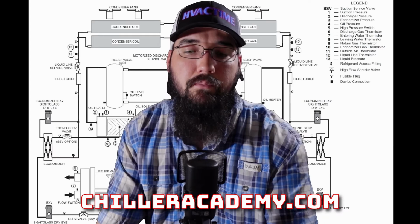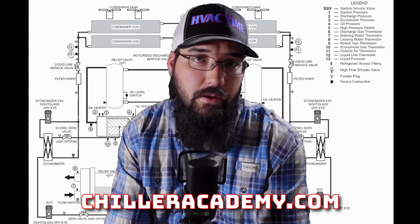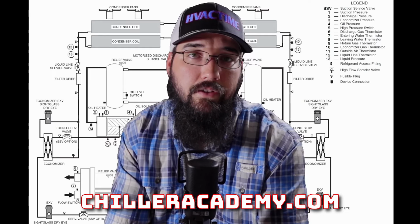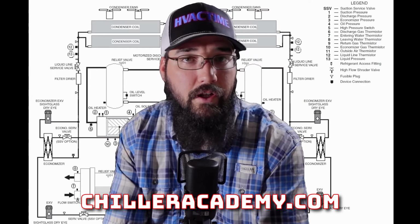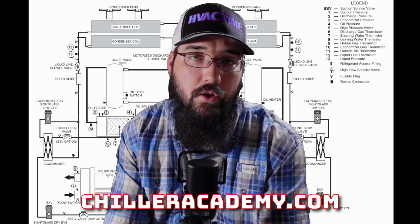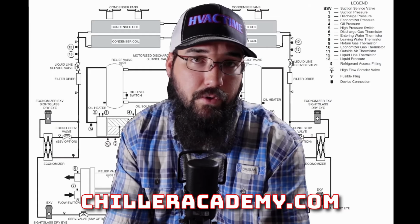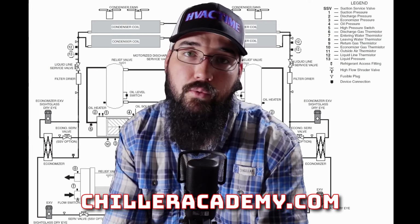So they'll put both together in the same compressor. Essentially, what that typically looks like, they'll use the slide valve as the first loading point. So the compressor will start at a minimum speed, and the slide valve will be at fully unloaded. Then when the compressor goes to load, they will load the slide valve to fully loaded, and then the compressor will slowly begin to ramp in speed from there. And those are your two main control points.